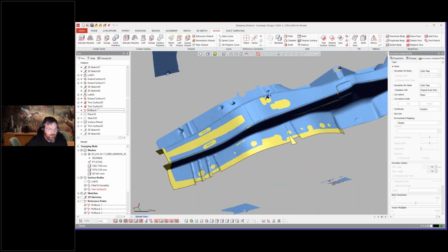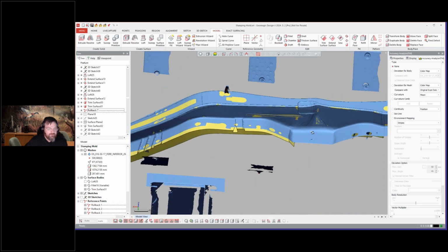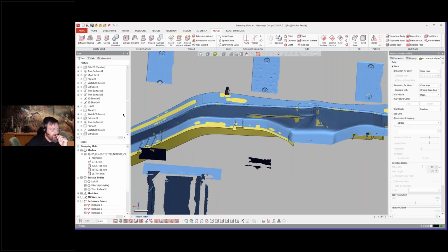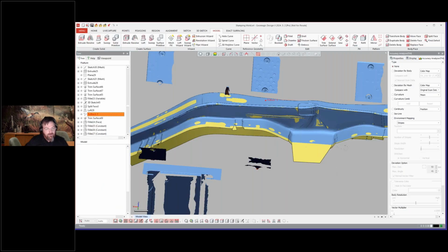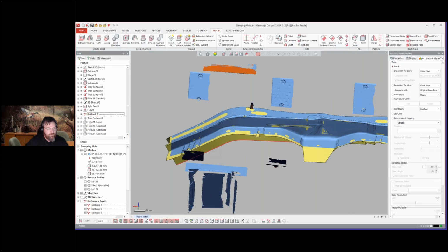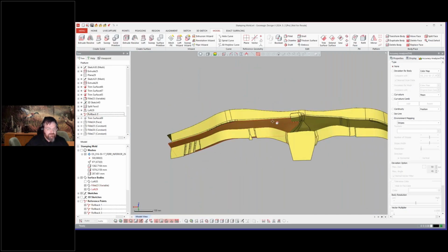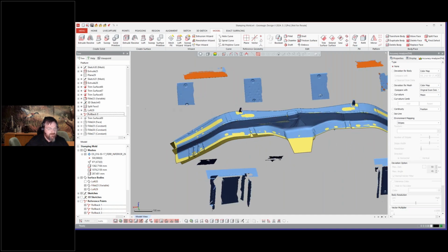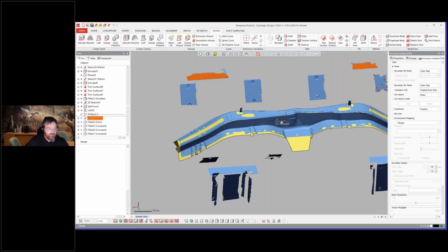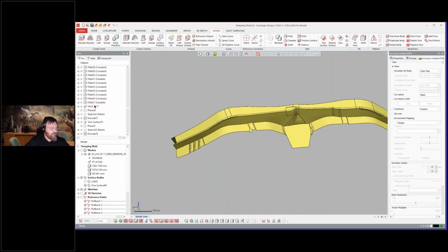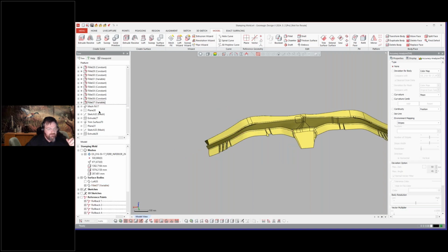So we went ahead and we modeled all of these trims all together. Wonder how many trims there are in this whole project here. It's quite a few. So we trimmed all of those together, and then they continue on through to the other side. So we trimmed all of this together into a big old surface. It's still separate from this one. We haven't trimmed it in yet, which is coming up here in a second. If you go forward, then this all gets trimmed in with that. And then obviously you'll see here that they add all of the fillets, and then keep moving. So you can see just breaking it down into the separate pieces of surface trimming.